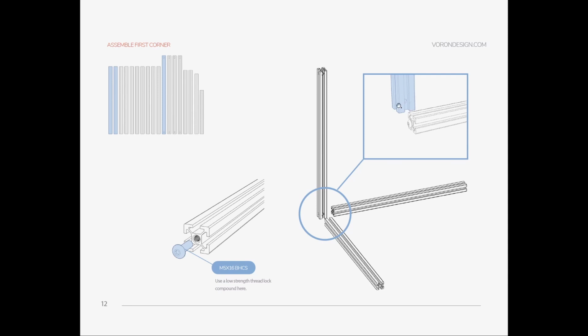But be careful about these hinges. Since the head is holding these hinges, you don't want to drill this part, but you can extend the hole. But the best option, like I said, is just don't bother yourself. What I would recommend is to just buy pre-drilled and pre-tapped. And if you are doing it yourself, just be careful about the position.